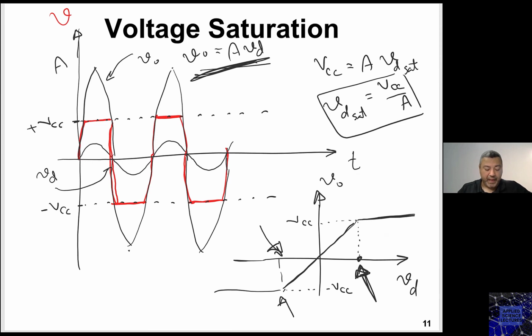That's correct. Here, I'm just talking in general about an operational amplifier that has an output in phase with the input, which is basically input is positive, output is positive, and then it's clipped, reaching the saturation due to exceeding the maximum and the minimum gain. Right? Make sense?